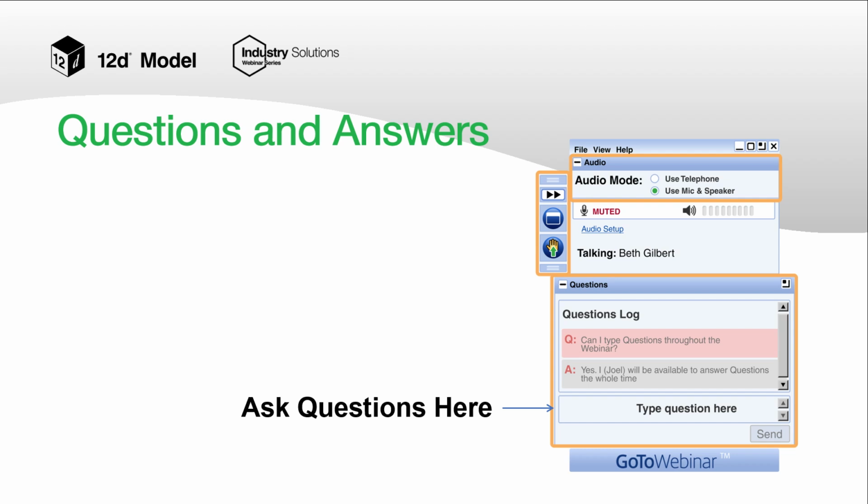Okay, great. And we'll just do a couple more. So Xavier has said, what did the different terrain options change? That was our attempt at getting presets for the levy tolerance. So selecting a terrain, all that does is it uses a preset levy tolerance value in the field directly below. So if you don't want to worry about typing in values yourself or remembering what numbers you perhaps want in the levy tolerance field, you can just select a preset and go away and make your catchments. So that's all it does, it just configures the levy tolerance.